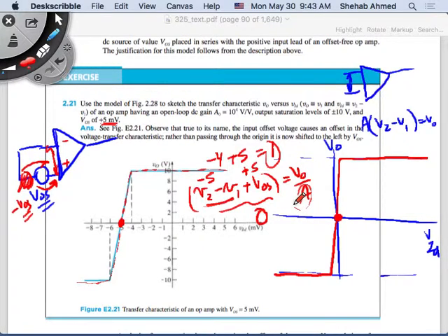Is that like a safety check to make sure that if V2 and V1 don't equal each other, it won't saturate? Or what's the purpose? No, this is something that would exist in the op-amp physically. Because remember, this op-amp is not an ideal thing, right? The op-amp is made of transistors and resistors and capacitors inside it. This chip is made of devices inside. Okay, why did they add the offset voltage? They didn't add it. It's a manufacturing process. Yeah, but then why is it zero? This is chapter 12.